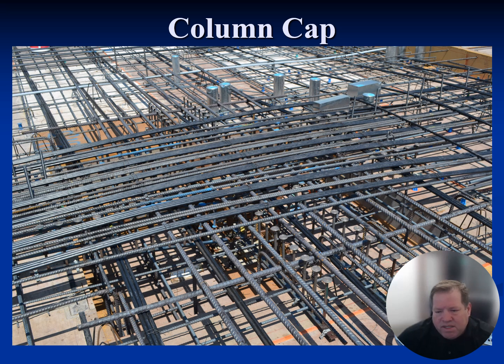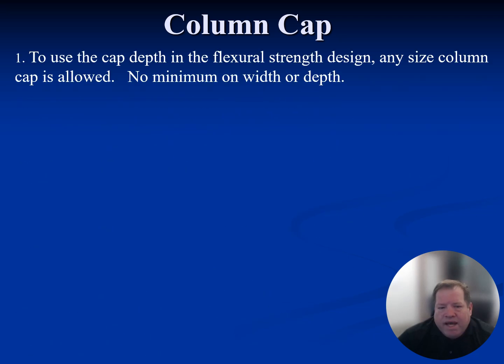Banded PT over the top, uniform direction PT. There's a lot of stuff in these podium slabs, but the cap adds a lot of extra depth, which is obviously an extra d value for your bending stress, or bending strength. The depth of the section will increase, the cross-sectional area will increase, and the S will increase. And the S increase is really what buys you a lot of forgiveness in post-tension designs. Now, the one thing about caps that is very different from drop panels is that you can use whatever you want.